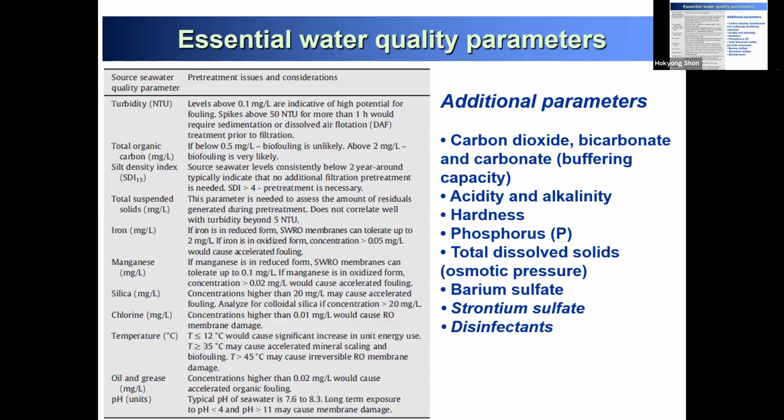Pure water and salty water have different concentrations, so we say this is the osmotic pressure difference. If you have a higher concentration of salt, you need more pressure to separate your water molecules. If you have less TDS, you have less osmotic pressure, so you apply less pressure for your reverse osmosis.